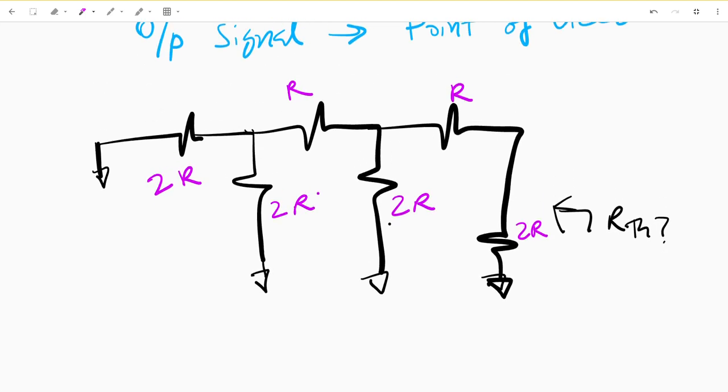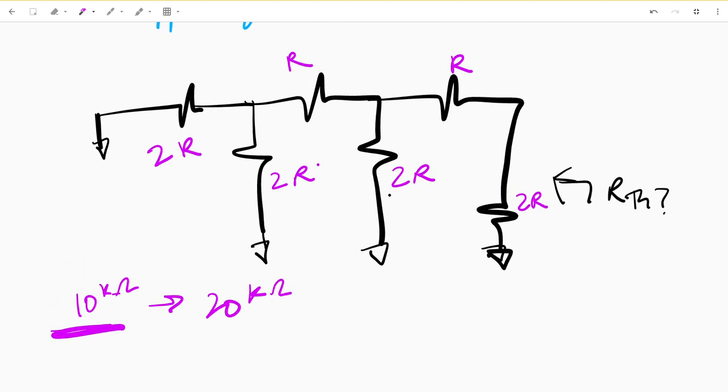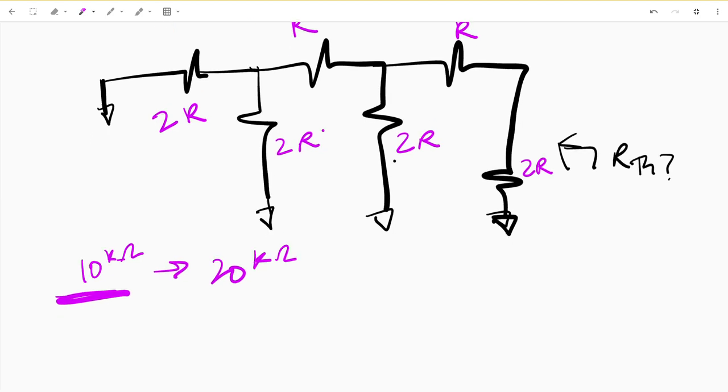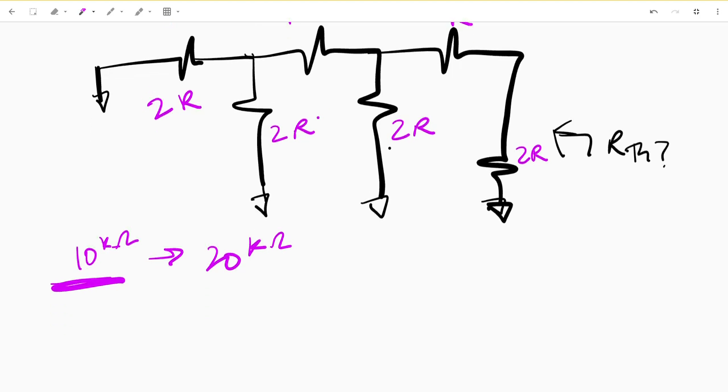And this is one of the benefits of this circuit, is you only have two resistor values. So if you pick a resistor value of 10K ohms, your other resistor value will just be 20K ohms, or 2 times 10. So that makes it easily fabricated, which leads to high accuracies, as well as low in cost and not as cumbersome.